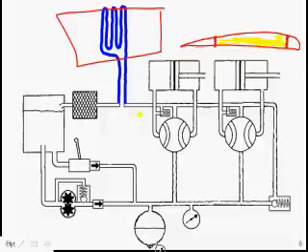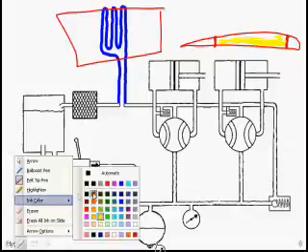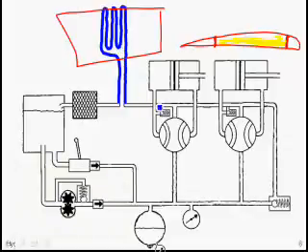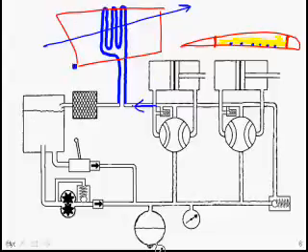What you can do is, you'll notice here, make it blue. On the fluid's way back to the reservoir, instead of running it just through the filter, you can run it through a fluid air heat exchanger, stick it in the wind outside and have air blow through it, or you could put this tubing inside the bottom of the fuel tank. If we looked at it from the top, it would look like this right here. But if we looked at it from the side, all the tubing is on the bottom of the fuel tank. So even if the fuel is low, we're still going to slosh fuel across the hydraulic fluid.